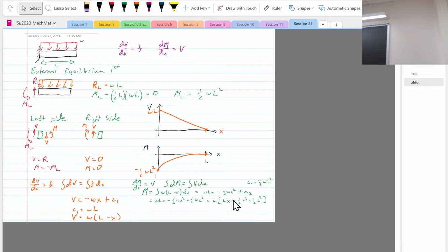So that one is contributing a bending moment, right? It's also shear force too. No, so PX, there's no x. If I move it over to here, it'd just be a normal axial force, right? So it's also contributing a normal stress in the x direction of PX divided by the cross-sectional area. So that is everything that PX contributes.